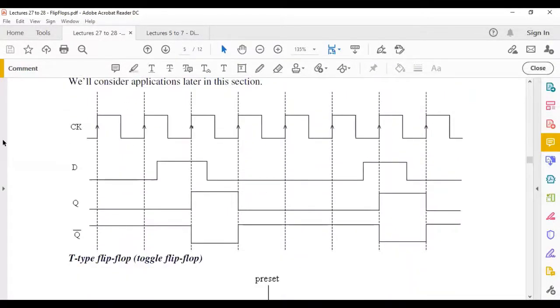But this timing diagram shows that very well. For every rising edge in the clock, whatever is on D is transferred to Q, as you can see here. Important here, for example, you see that segment here. Your D has changed state, but your Q doesn't change state because it can only do that in synchrony to your clock. So only at the rising edges does the circuit check the state of D and transfer that to Q. So that's an important point.